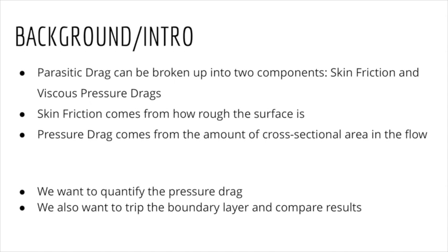Although the drag force will increase with an increase in velocity, the coefficient of drag could actually decrease due to the inverse relationship between the force and the dynamic pressure in the coefficient of drag equation.